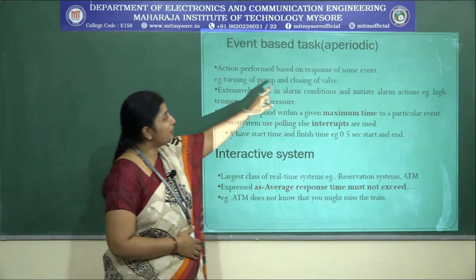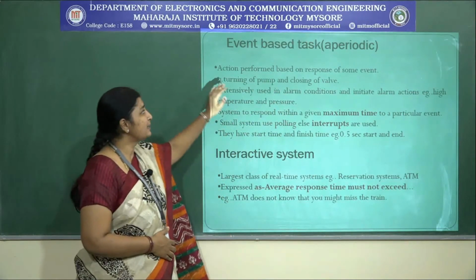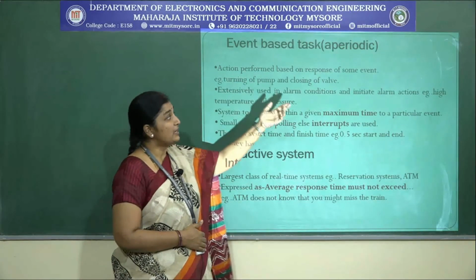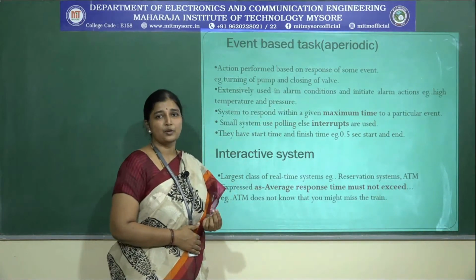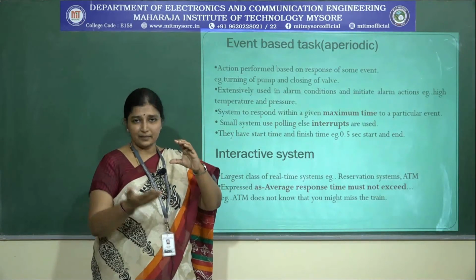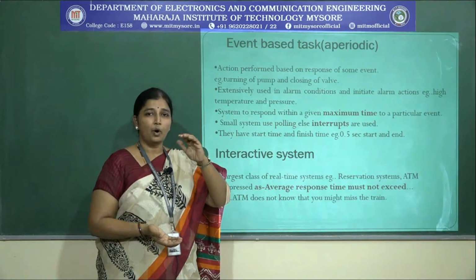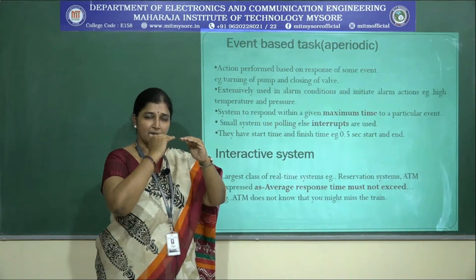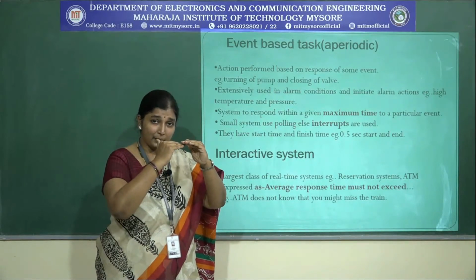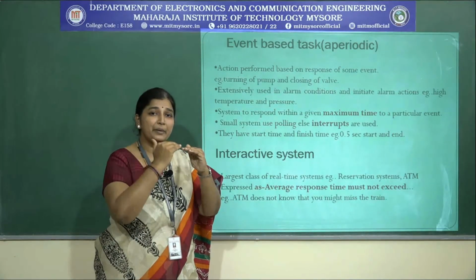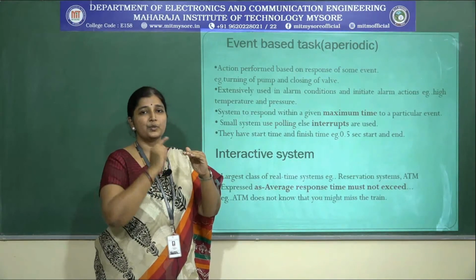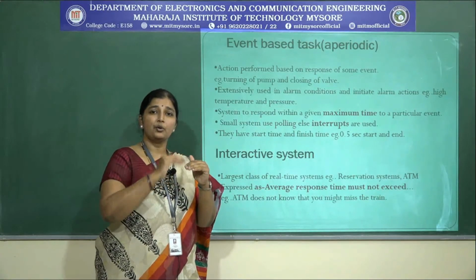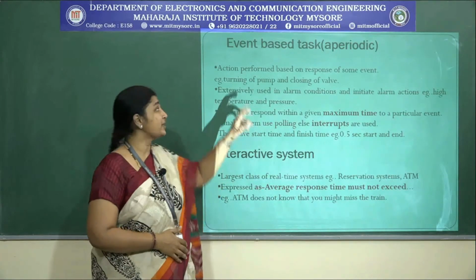So it is the action performed based on the response of some event. For example, as I've told you in the previous example, the water level has reached from the bottom to the top, and if it reaches the valve, at the ball point, what will happen? You say that the event has completed. So what happened after that? You have to switch off the switch, right? You turn the switch on, off, and the valve on, off. These are all based on events.